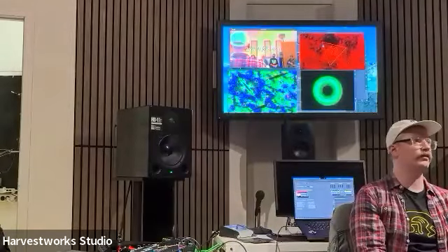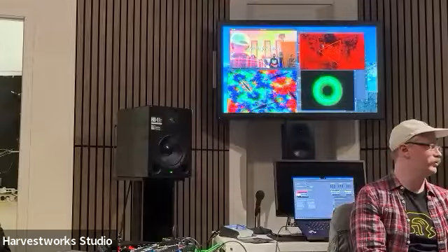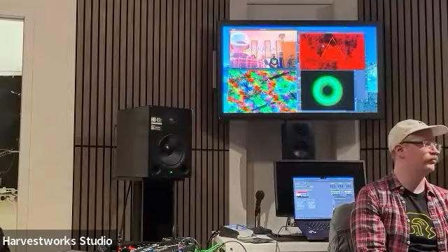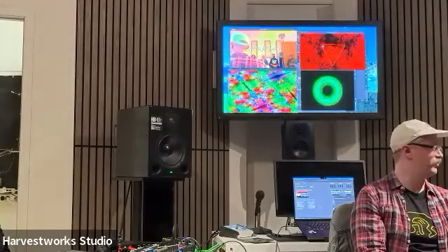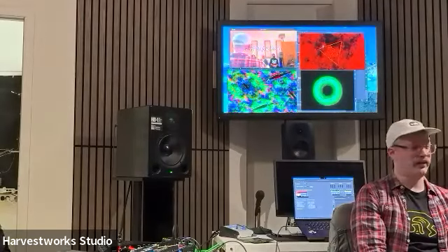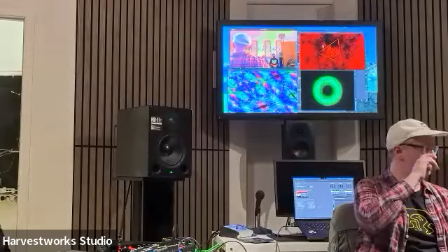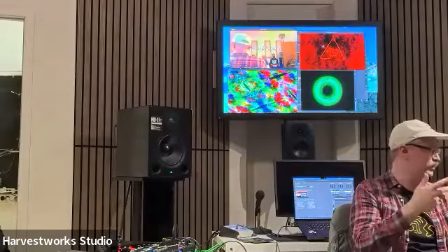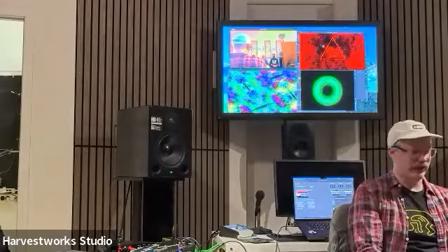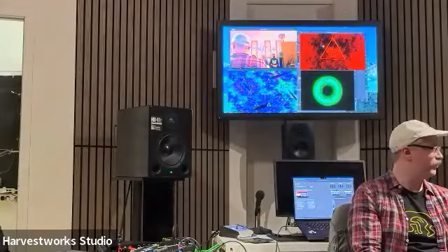Also, I know a lot of video synth modules, like LZX, work with plus or minus 1 volt. Yeah, the video stuff. So you can take that 0 to 5 and make it plus or minus 1. Yeah, and then attenuate and plug that into your modules and it will work just fine.